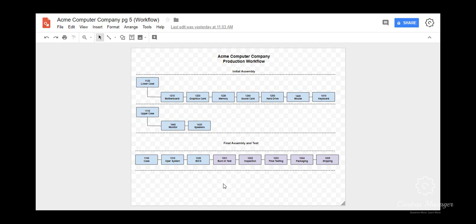So I hope this was helpful. And this is generally all that is required for this project. Basically, just make a general workflow. I showed you how to make a bill of materials, which is very important for a lot of things, just to identify all the materials used in construction. It's also used for a work breakdown structure, where it catalogs all the work being performed on a certain product. And it's also used for managing things like drawings and other processes.